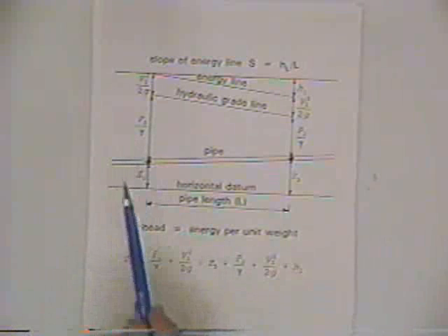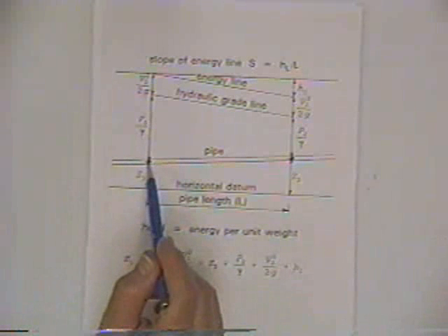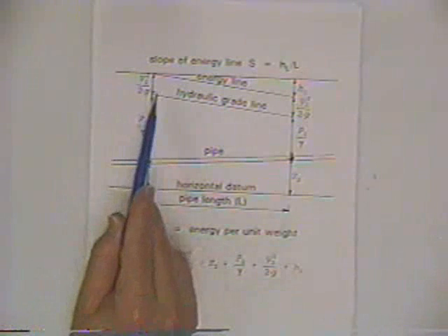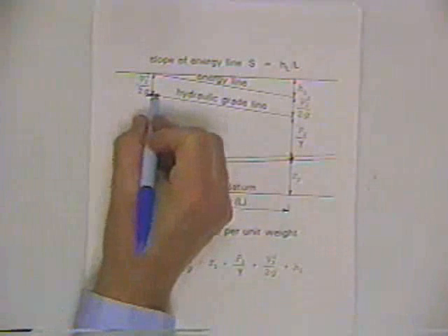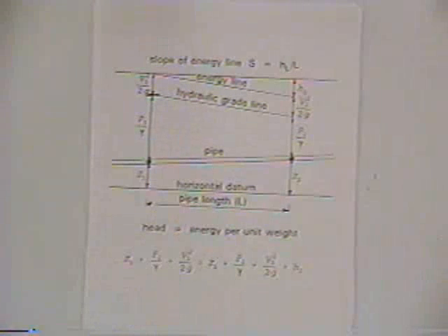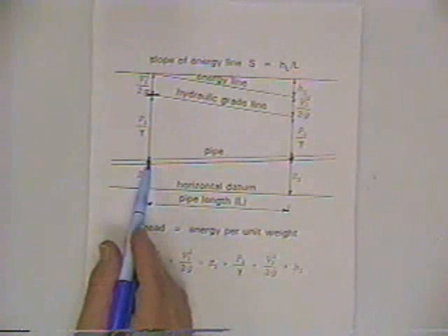It has some pressure, and so if you can visualize the pressure, if you drilled a hole in the side of the pipe and inserted a piezometer tube, the water would rise to right there. By definition, that's your hydraulic grade. That's how high water would rise in a tube that was inserted into the pipe. And that's why we call it a pressure conduit, because you don't have a free water surface at atmospheric pressure.